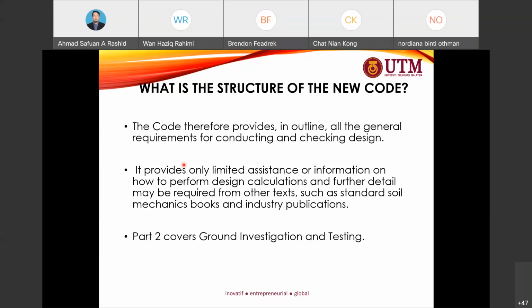For example, for the bearing capacity of shallow foundations, we still use the Meyerhof or Terzaghi approach in the design. However, there is a slight difference in the approach, by using different partial factors of safety in the design compared to the British Standard approach.